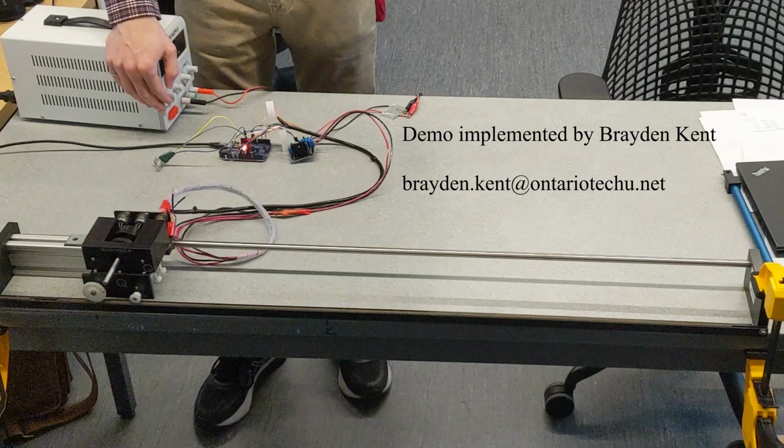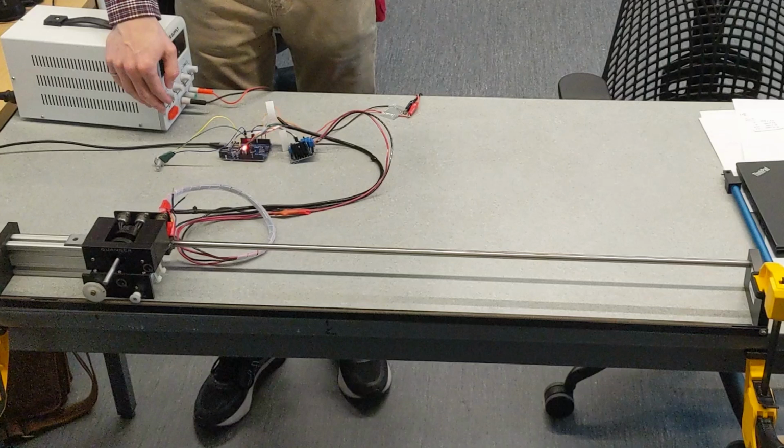First, we are going to try that with a proportional controller only, then with a proportional and integral controller, and then finally with a PID controller. Two things can be observed. The first one is when the cart is let go from rest and reaches that position, and the second one is when a disturbance is applied. In this case, the disturbance is simply a manual displacement that is applied to the cart. The Arduino code used in the lab to implement this controller is available on Canvas.